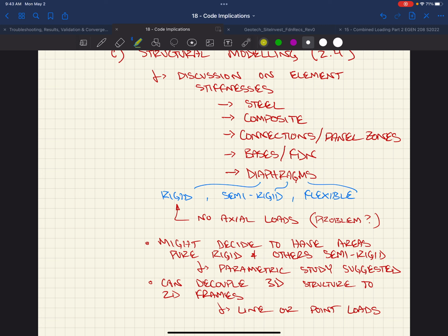right? Well, if we're assuming this diaphragm stays the same dimensions, we're going to be holding all of the members that are in that diaphragm to those dimensions. You're no longer going to be able to strain them. You're no longer going to get axial forces out of them. Where a lot of times we have axial forces, based on dragging load into something or dragging load out of something.